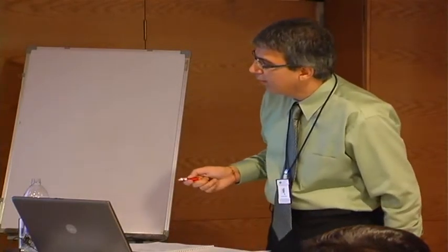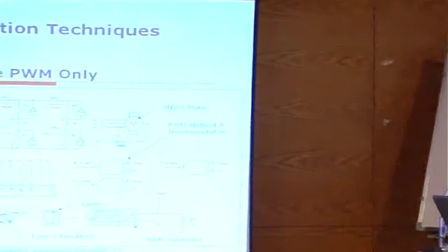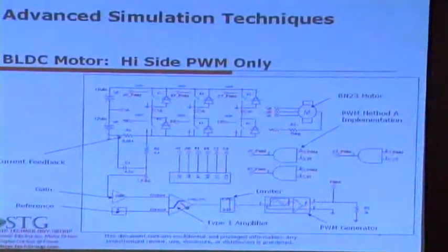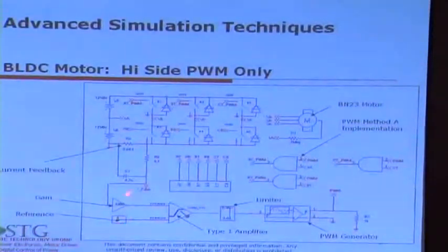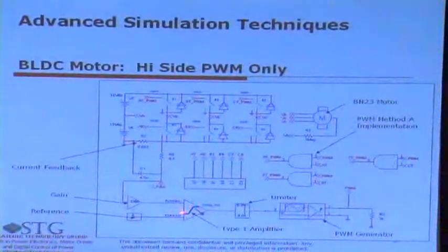What's the reason for R2C1? R2C1, basically the reason for R2C1 is to filter out the high frequency from the resistance. Because you're comparing with a DC reference here, you want to essentially have a DC feedback. Probably to block out the diode reverse recovery spike. That's one reason also. That's another reason also.